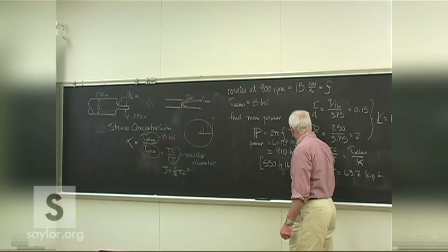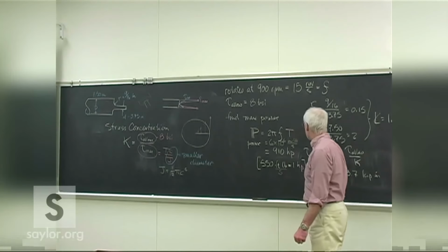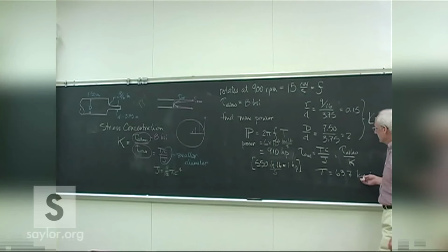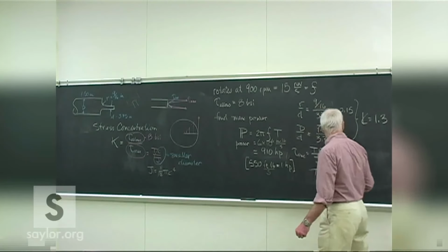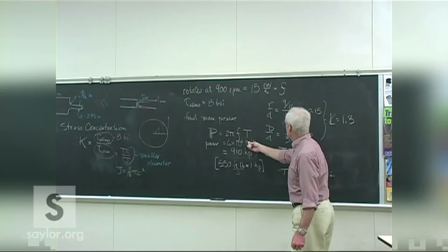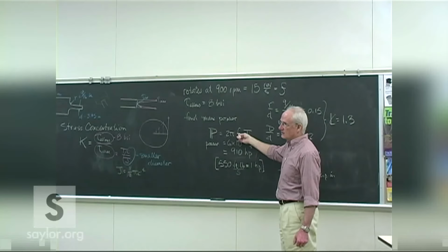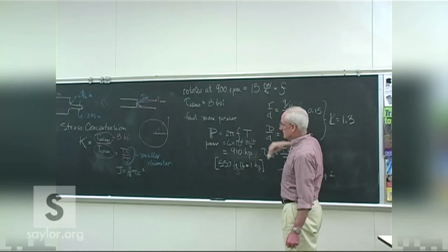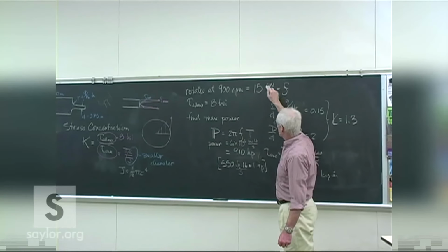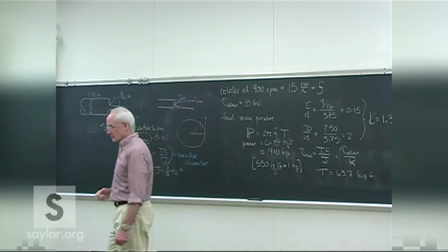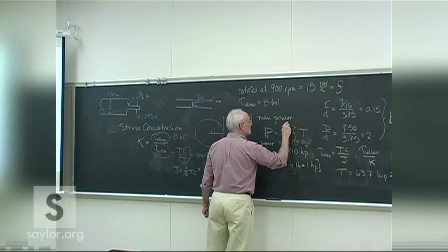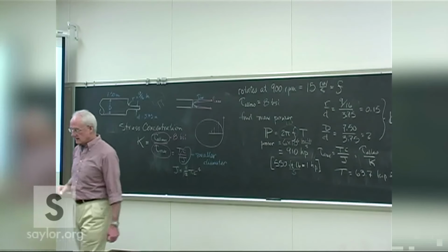And so we have 63.7 kip-inches over here, and that goes in here, so that becomes units of something like, depending on where your decimal place is, inch pounds per second, because the frequency is in per seconds. The 2 pi here handles the revolution, but it's actually radians. So then you convert the angular velocity.